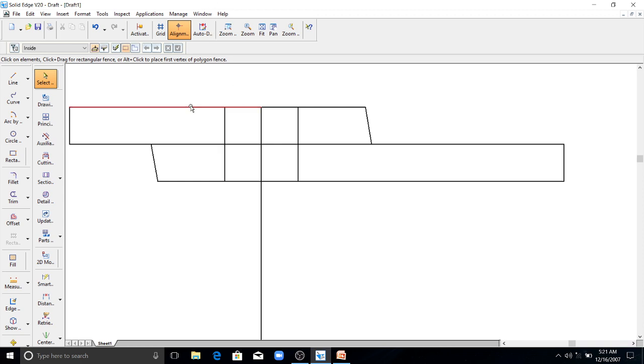So now you have to draw the snap head. The radius of the snap head is 0.8 D. Before drawing that snap head, you need to draw the radius. For that radius, you need a particular center. So I will tell you how to draw that center. First you have to take the height of the rivet head. The height of the rivet head is 0.7 D, that is 12.6 mm.